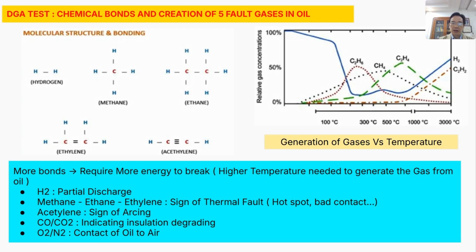In some cases, with oil leak and high moisture, the BDV of the oil is reduced. BDV is the breakdown voltage of the oil. For a transformer, the BDV should be higher than 40 kilovolt. If the BDV is too low, the insulation of the oil becomes bad. Then at a certain level, discharging, arcing, or even total burning of the transformer might happen.